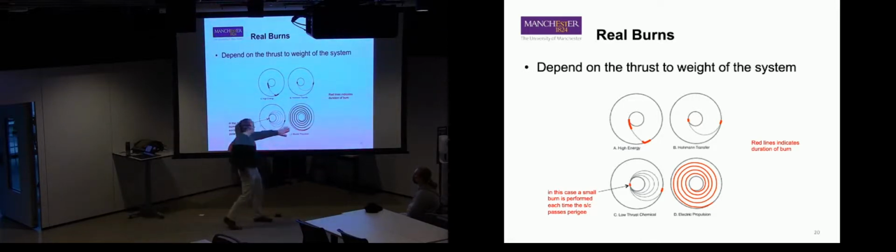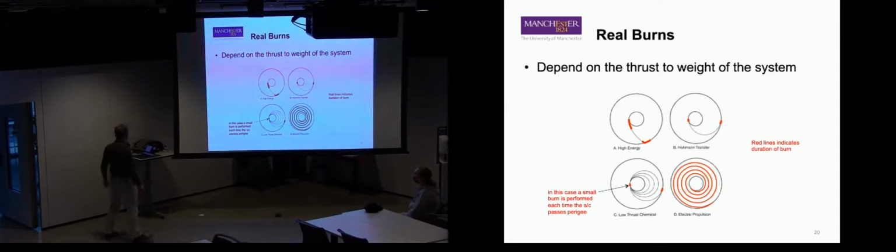Electric propulsion, low thrust chemical, we've got to do more sophisticated. Nice thing about low thrust chemical, if we can turn the engine on and off as much as we want, we just repeatedly burn here, here, here, and intercept at the minimum delta V change required. Or electric, which is even lower, the nice thing is we'll just continuously burn. If we have higher thrust, high efficiency electric, we can do high energy stuff and burn all the way, flip it over, and burn the way back in. Okay? Pretty straightforward with that.